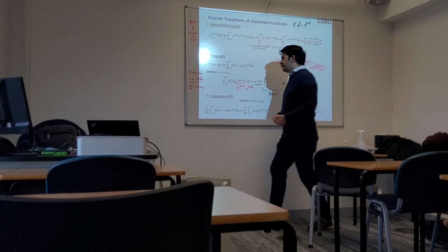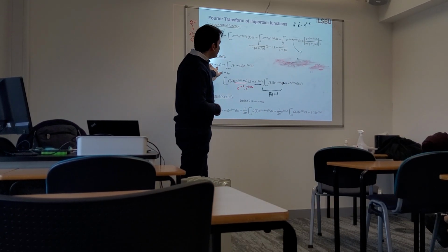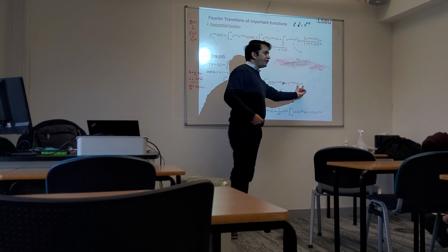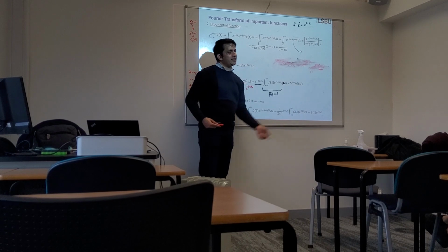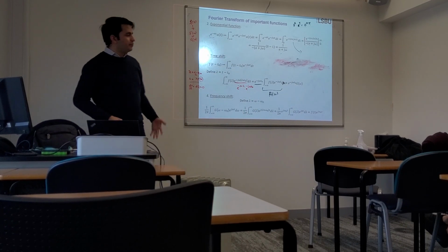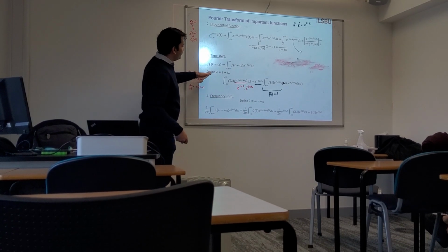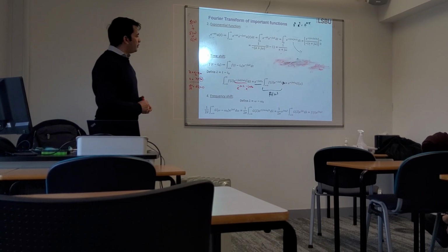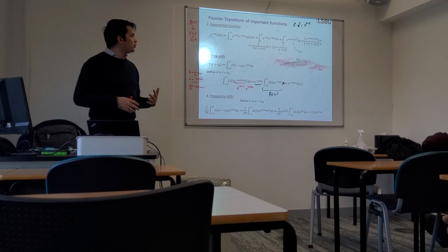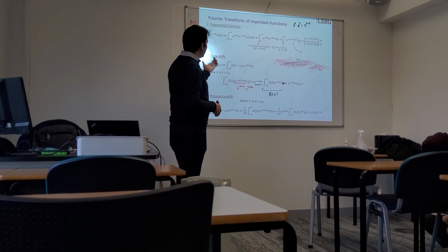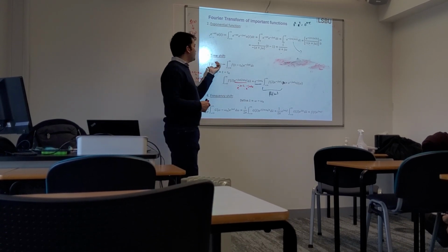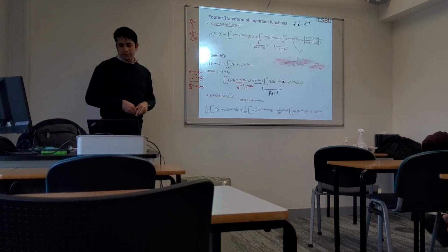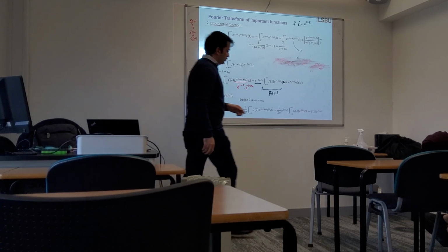So it means that we came to the conclusion that if you have a time shift, the time shift would result in a Fourier transform of the same function with an extra term, which is e power minus j omega t naught. But to find this, we took the help of replacing the variables with the new variables that we have considered. But even if you don't know the derivation, still it is fine, because this is our main objective, to find simpler ways to solve our Fourier just by taking these formulas.